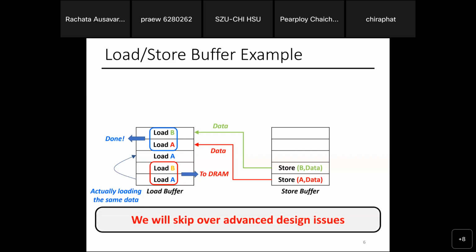All right, there are many issues about advanced design. For example, I said it's a load 2A, but sometimes I don't know where I'm loading to. It's basically I'm loading the value that is in this register, which is dependent on another previous instruction. So I don't know the address I'm loading to. The question becomes, do you issue right now and guess? Which you can actually. Modern CPUs actually do a lot of this guessing the address. If you're correct, yay. If you're not correct, throw it away.